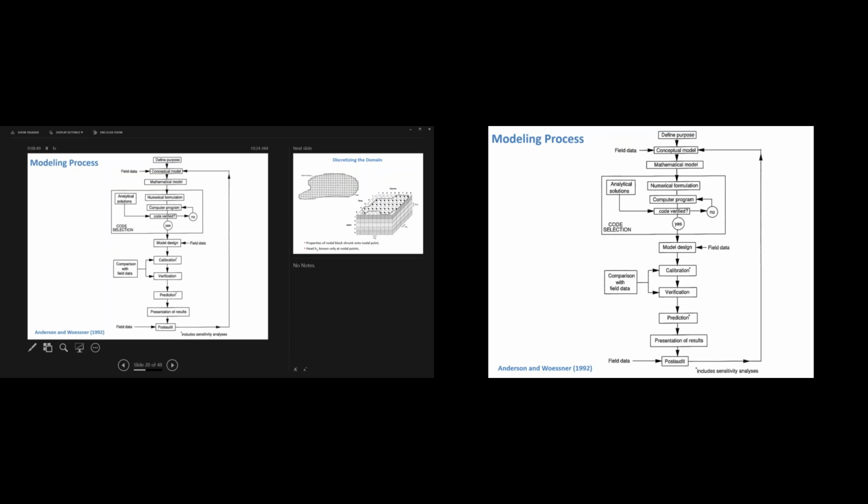Yeah, it's a lot easier to build a small model you can test and have it run in a few minutes than to let the big regional model run, it takes 14 hours, and then you realize, oh wait, that's not doing what I want. That should be a 4 instead of a 5, or if it's a big model, you don't necessarily see the impact of what you've done. Right. So you've got to set up your little test case, like with a big hydraulic gradient or a big pumping stress, so you really find out what's going on.